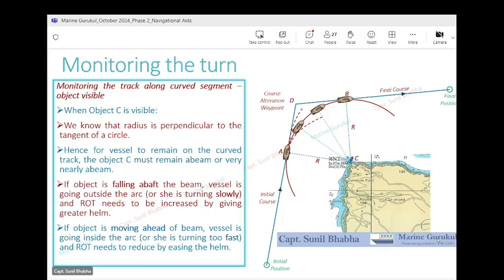Yes, sir. Yeah, there is a certain drift angle during turning. The heading of the ship is not exactly in line with the course being made good. So that much is neglected, beta. We don't go that much deep into it. You can conveniently neglect it without any appreciable loss of accuracy. Okay, sir.